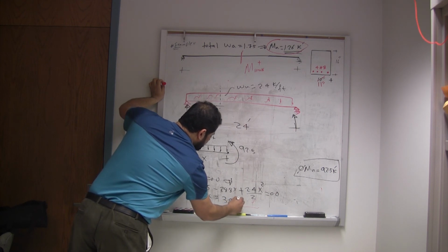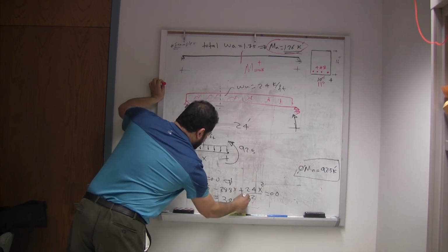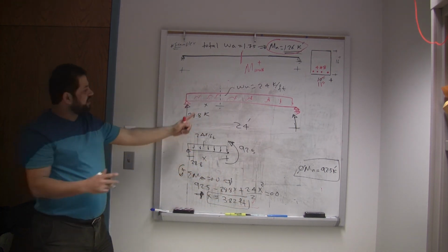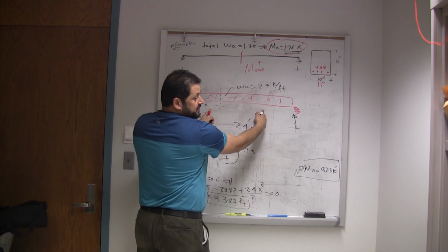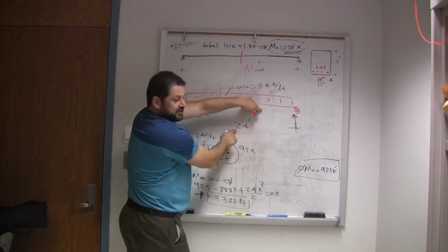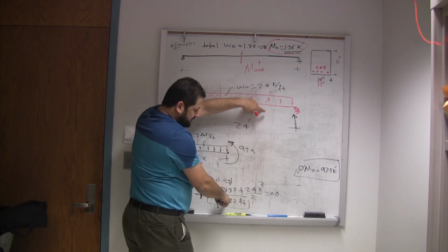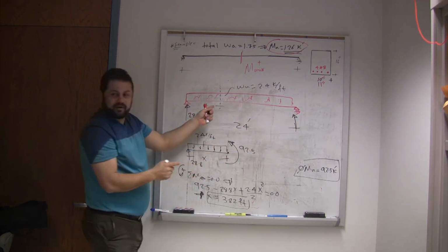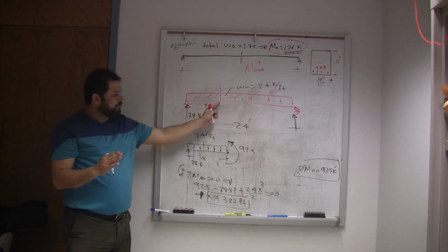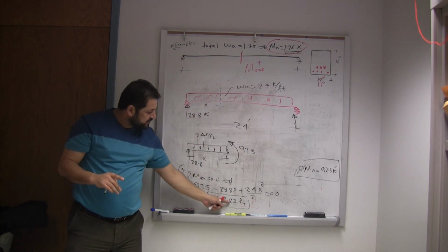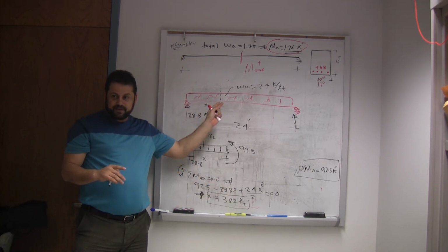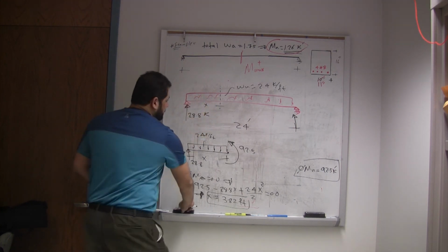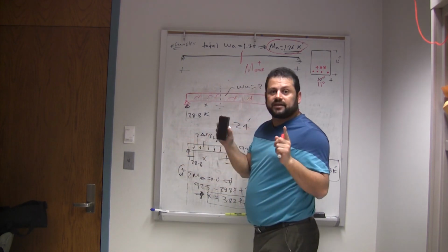3.82 foot from the left end, by the way. You'll find two values. The other one is 20.18, which is 24 minus 3.82. So you found this and this, and one of them is enough. So you know that from each support, up to 3.82 feet, you just need 2 bars. Within the middle, you need that much. So now we know the theoretical cut-off points.